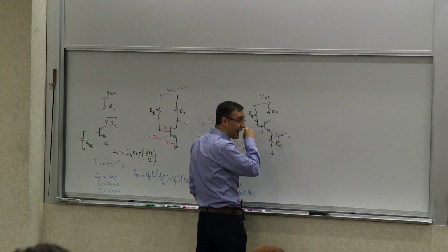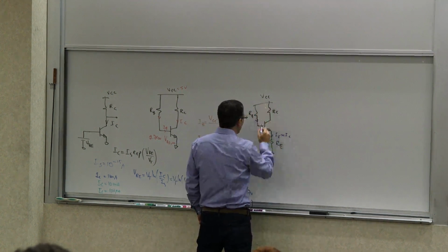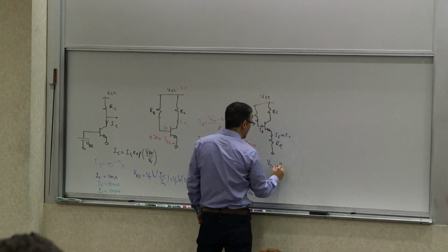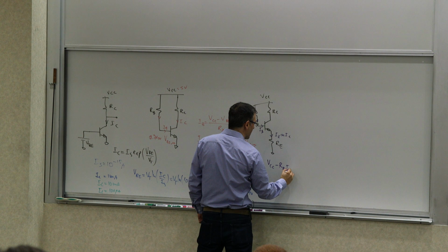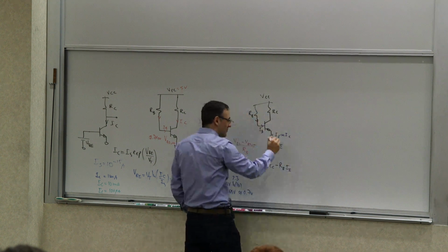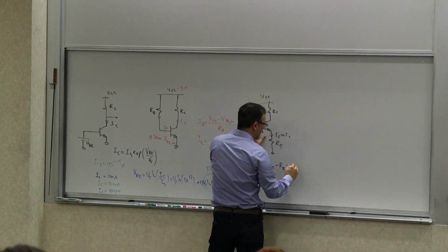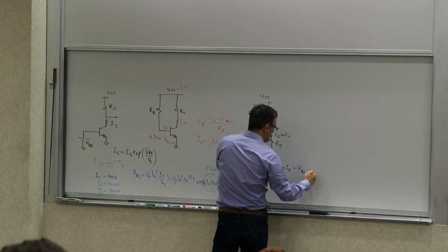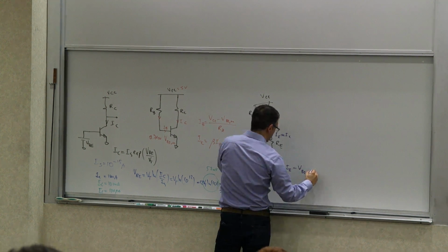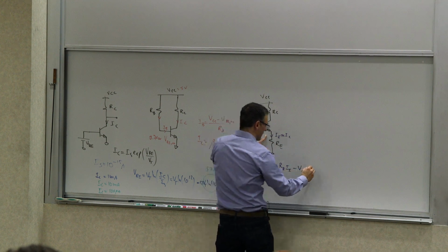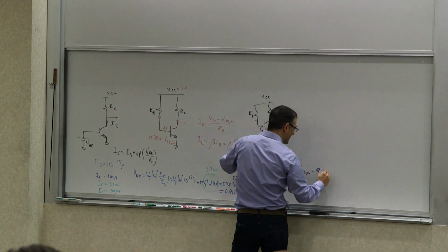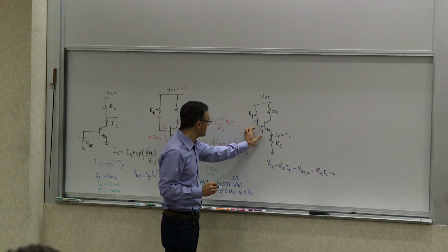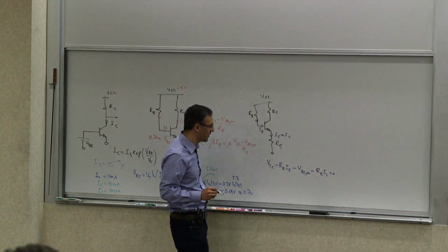Right? It's to a factor of alpha. So if you start from here, you can say VCC minus RB IB, which is the voltage drop across this guy, right? Minus VBE on, which is the voltage here, okay? Minus RE IC is 0. Right? So it's this voltage plus this voltage plus this voltage, which is VCC.